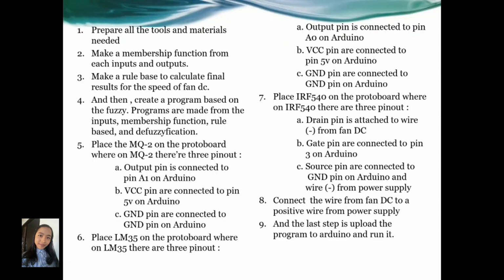Sixth, place the LM35 on the protoboard, where on the LM35 there are 3 pinouts. The output pin is connected to pin A0 on Arduino. The VCC pin is connected to pin 5V on Arduino, and the ground pin is connected to the ground pin on Arduino.